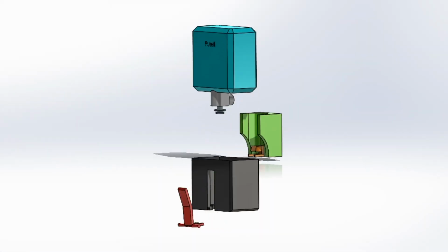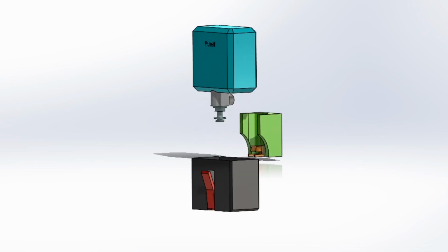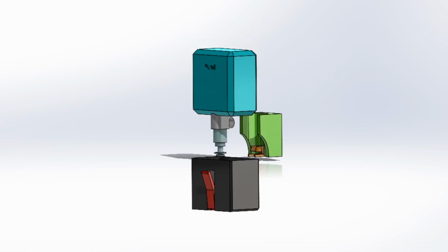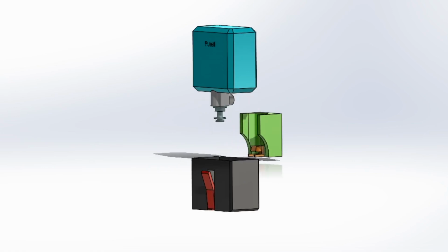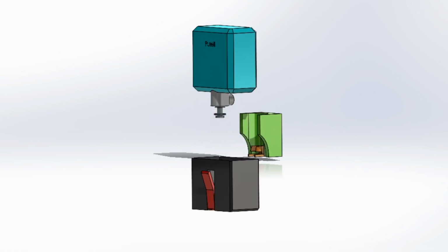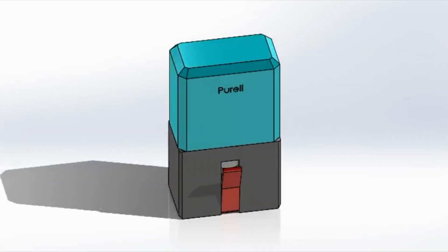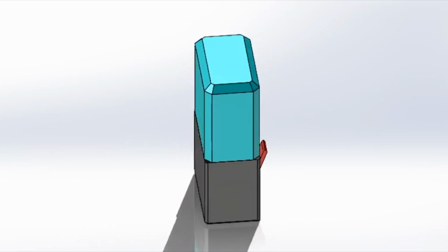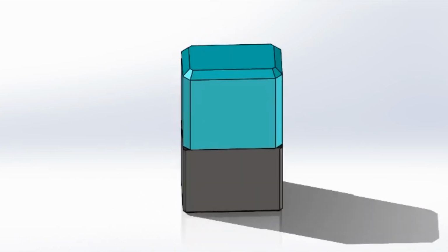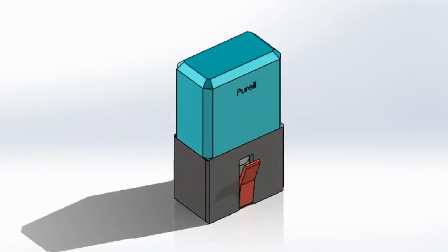Here is the exploded view of the soap dispenser with its new components. As you can see, the lever fits into the lid from the bottom. The axis of the lever clips into the slots of the lid. Then the lid is attached to the body the same as before. The lever has been designed in a way to avoid interfering with any of the internal components. Even if there are no issues with the automated function, the failsafe can still be implemented without hindering the system. So virtually, there are no downsides to adding the failsafe.